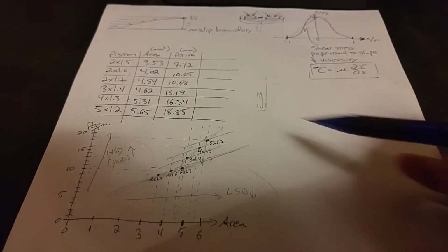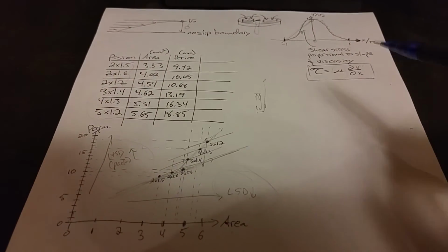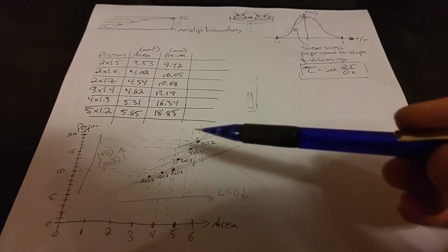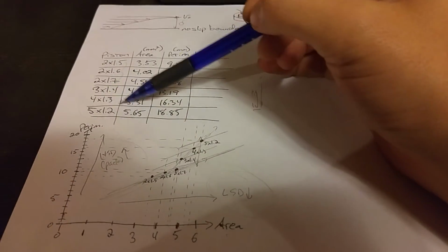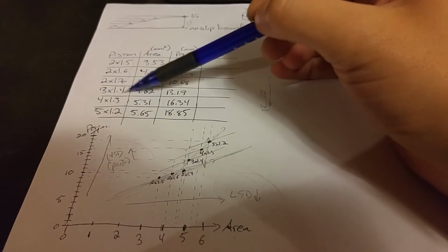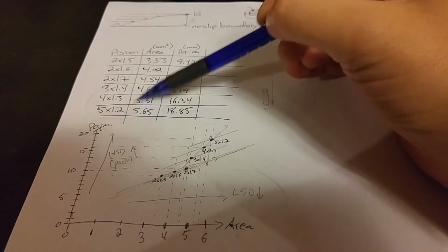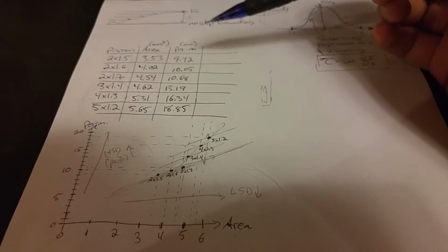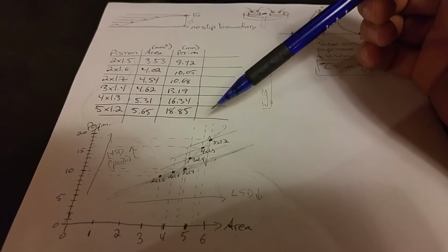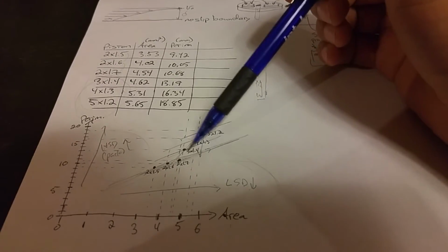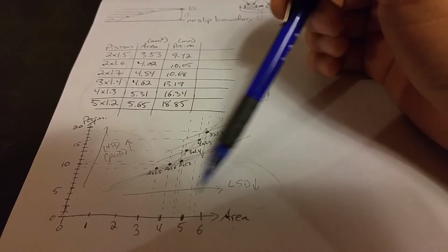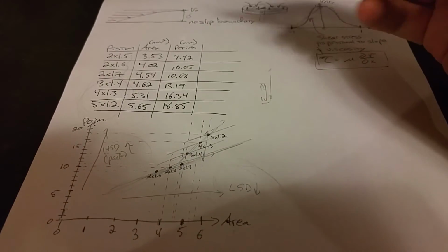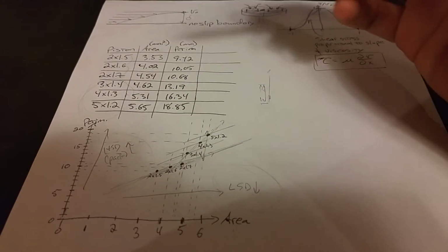That's all this is really doing for you here. So again, if you're on a smooth surface, you might tend to want to run something like a 4x1.3 or 3x1.4, something greater than 2 piston holes to give you a bit more pack, but also a bit more compliant low-speed damping here for cornering.